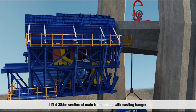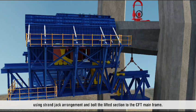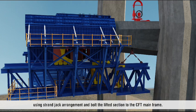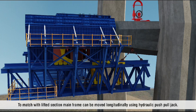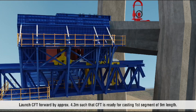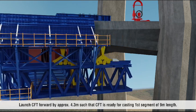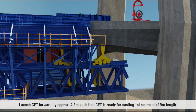Lift 4.384 meter section of mainframe along with casting hanger using strand jack arrangement and bolt the lifted section to the CFT mainframe. To match with lifted section mainframe can be moved longitudinally using hydraulic push-pull jack. Launch CFT forward by approx 4.3 meters such that CFT is ready for casting first segment of 9 meters length.